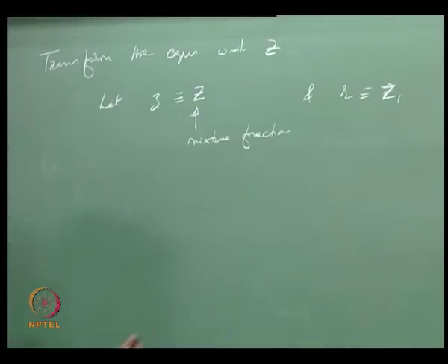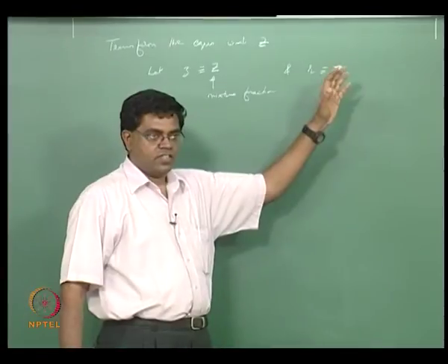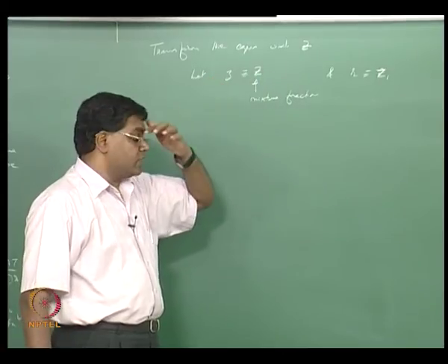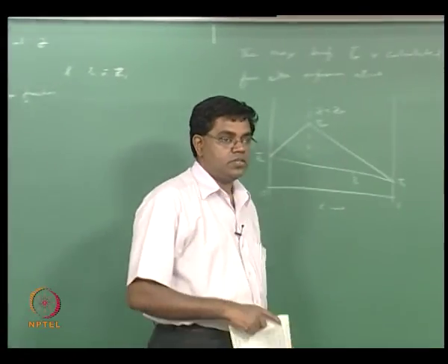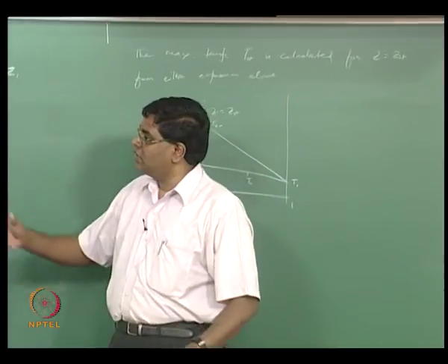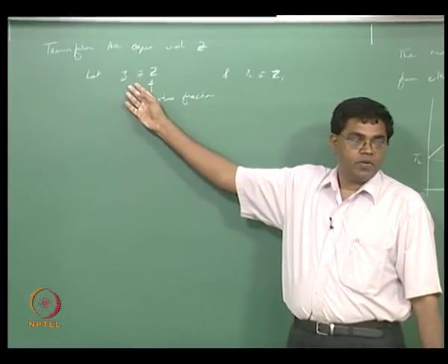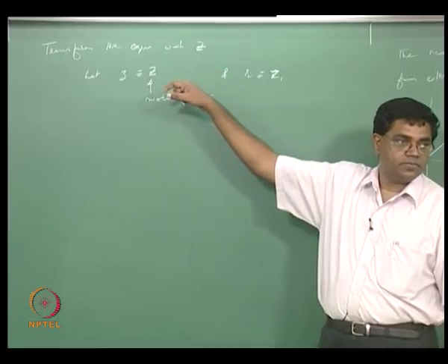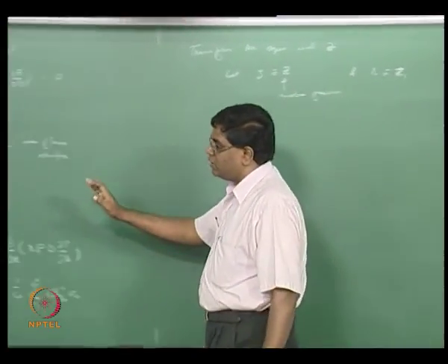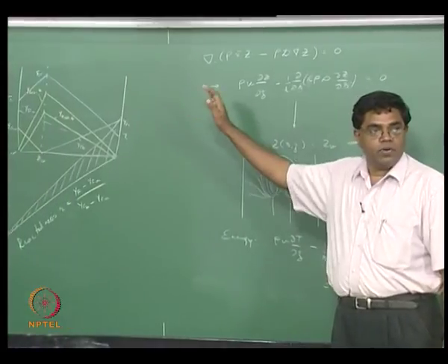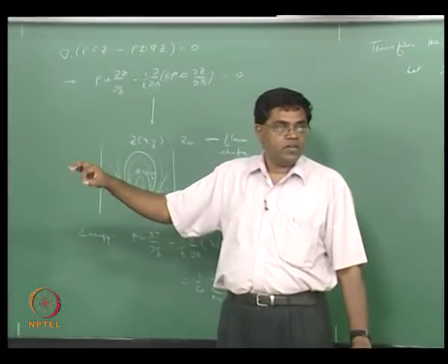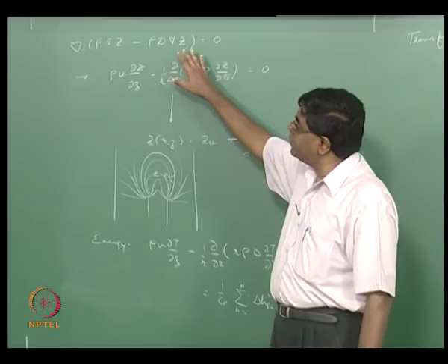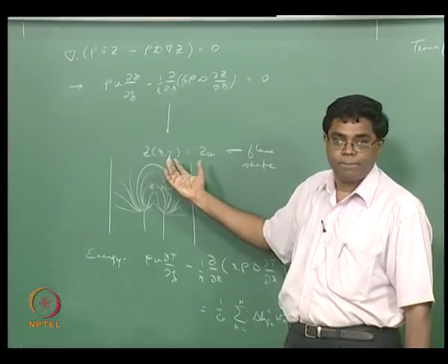So no big change there, just changing symbols, but here we are actually changing meanings, okay, and this is kind of like what's called the Crocco transformation, where you are replacing one of the independent variables by a dependent variable upon which you want other dependent variables to depend. So in all that we have seen so far, all the dependent variables that we are talking about are depending upon Z, and Z itself is governed by this, given that it's depending on x and r, right.